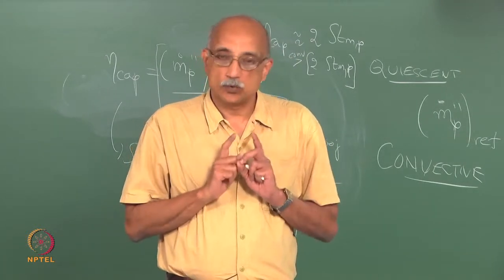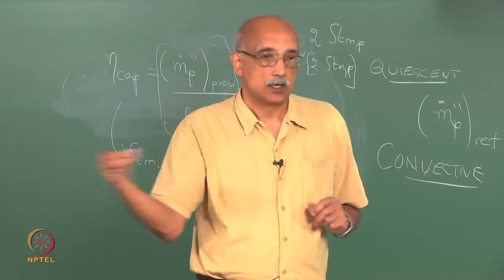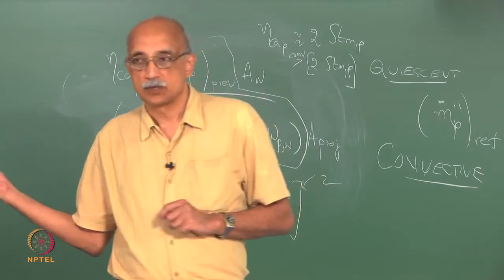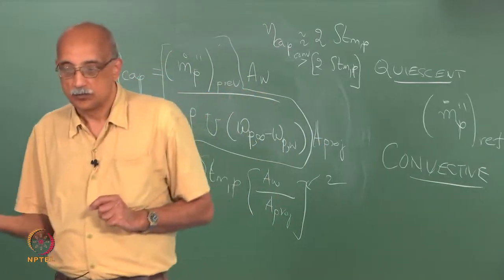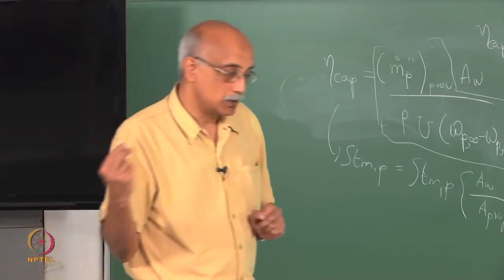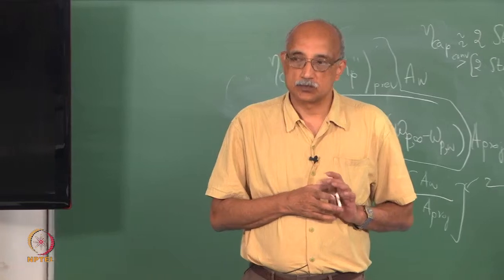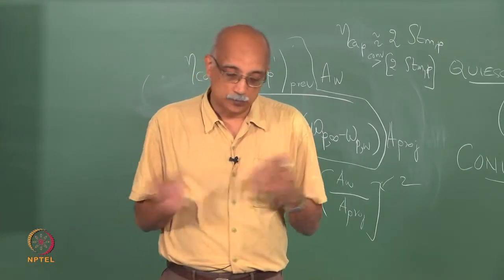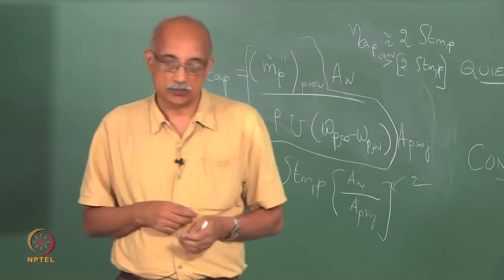Again, that can be done quite easily for measuring temperature. All you have to do is mount some thermocouples along the walls of the pipe and you can do heat transfer measurements on the fly. But as you can imagine, to do that type of work and measure particle concentrations as they are flowing would be extremely difficult. And so in situations like that, this analogy condition is quite valuable to us as a tool to be able to translate heat transfer data into mass transfer data.